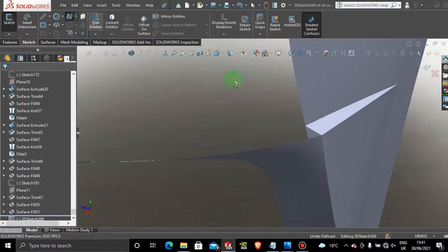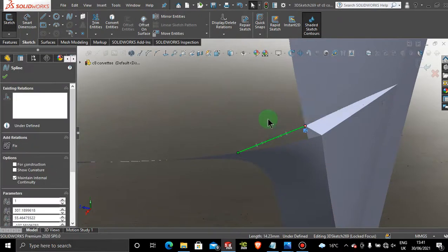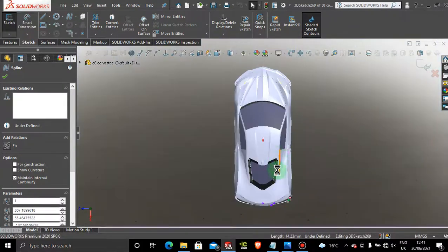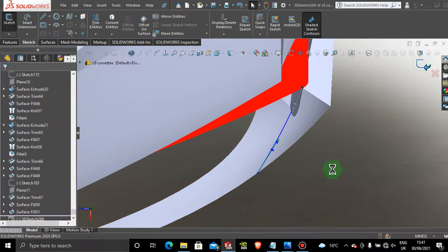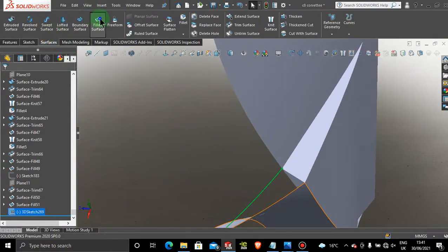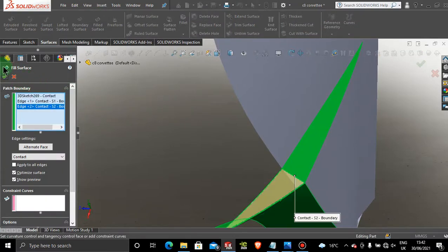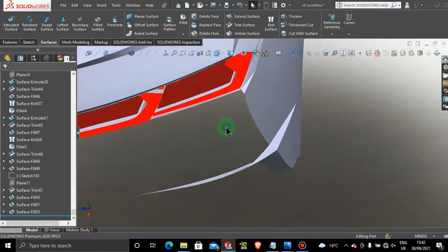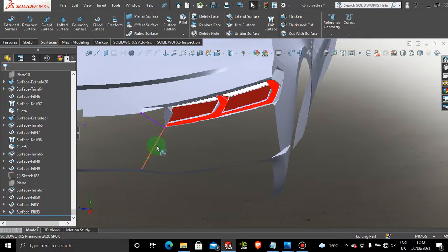3D sketch, 3D spline from this point to here, all the way out here, and we're going to add the profile back on. All right. Okay, jump in fill surface. That's already selected. This edge and edge here. Okay, great. And now remember this one is 3D sketch 236.